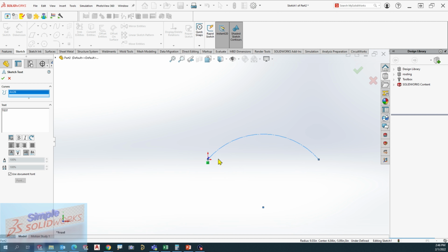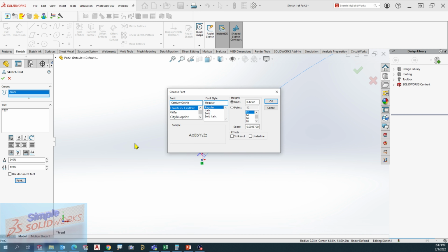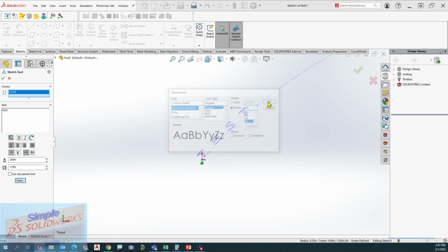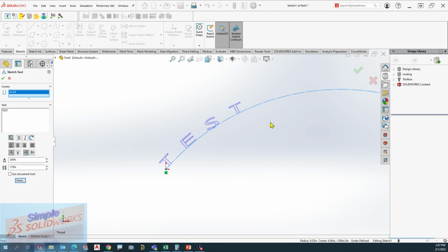And I think it's showing up, but it's very small. There it is right there. You can change the height of that by unchecking this little box right here. You uncheck that, and then you can say, well, I want it to be this way and that way, and then the font, I want to change it so that it's bigger. So you can come down here, say it's 18 points, and you say I want it to be 36. You hit OK, and now you have that.